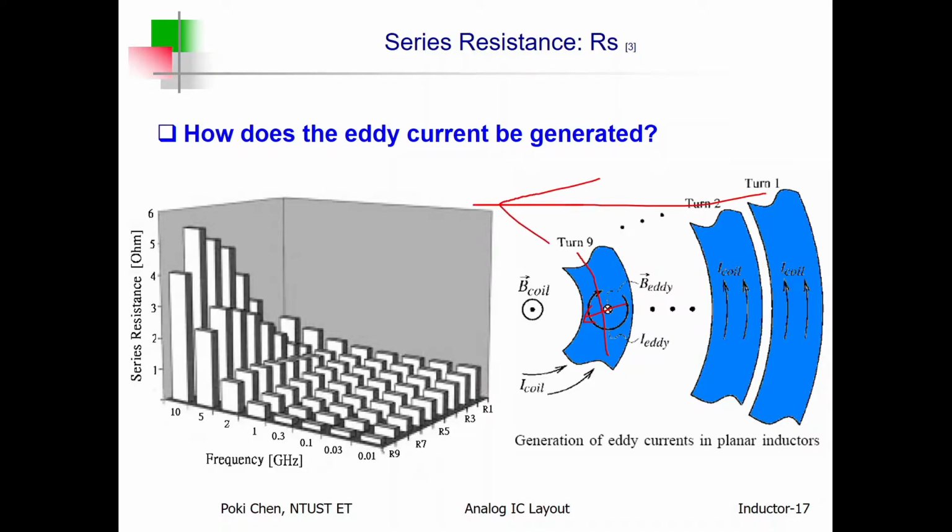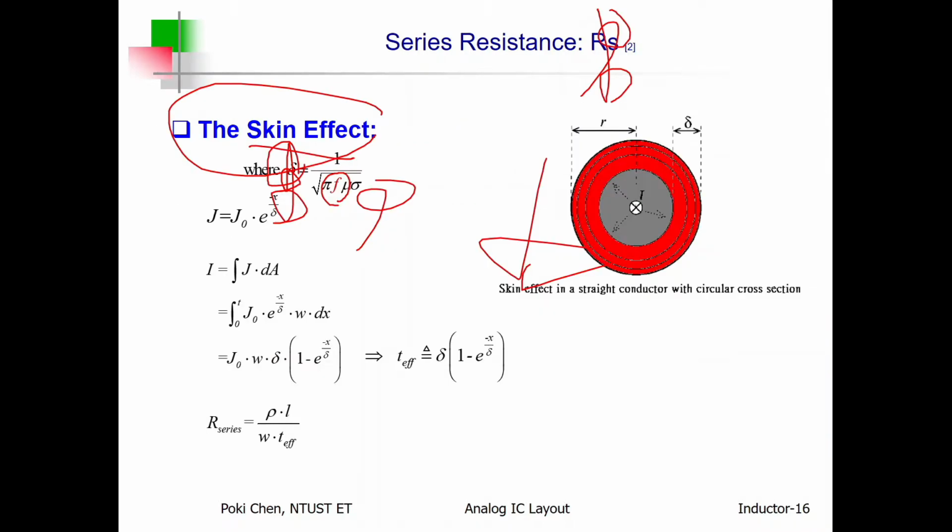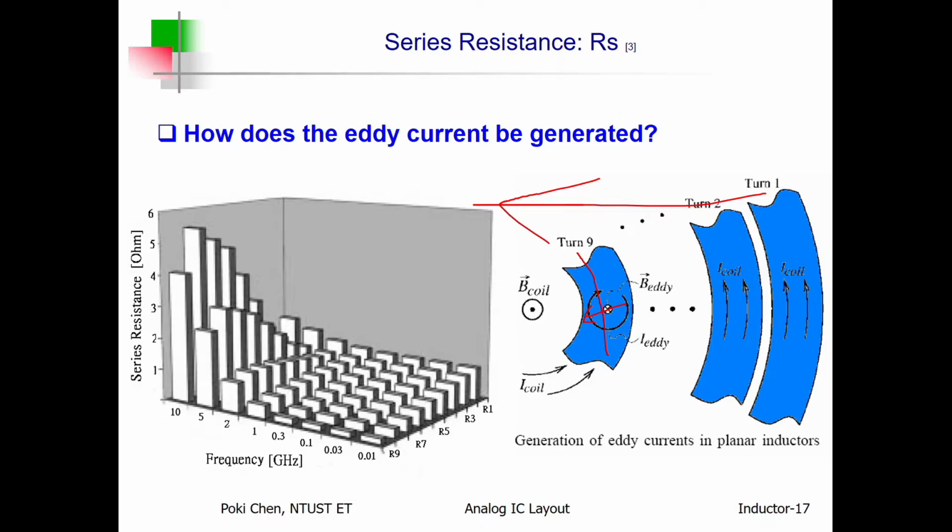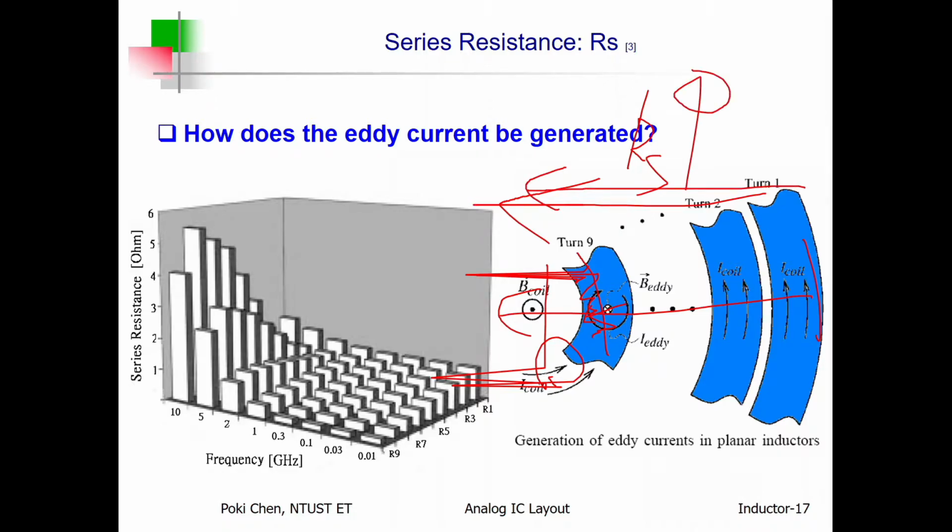Okay, briefly speaking, for the coil, the inner coil will get more impact through such kind of AC current or the so-called skin effect. It means what? The effective cross-sectional area for current conduction will be reduced from the outer to the inner. Okay, so it means what? The RS from the outer to the inner will be increased very much. Keep this in mind.